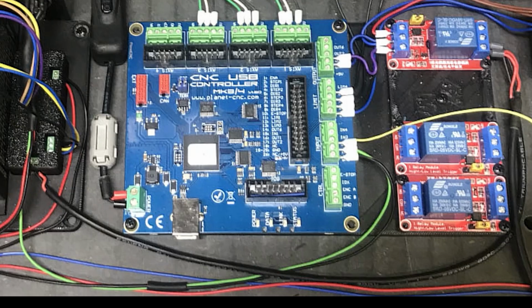The one thing about the outputs for the controller board is I needed to add this 5-volt relay up at the upper right hand corner. Now that gets powered with 5 volts and the common, and then this purple wire is the output. That's what's going to trigger the dust cover. I've got it wired on the normally open side because when the signal wire is pulled to ground, that activates the dust cover to open.